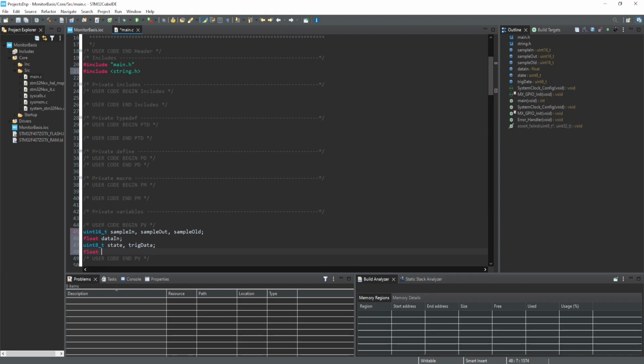So as you can see here, this basically creates in some memory address the data in as a float 4-byte variable. After this address, this will declare two 8-bit variables in the next address, and in the next address we created another 4-byte variable called data out for that output, and then you're gonna create an array to manipulate my data.